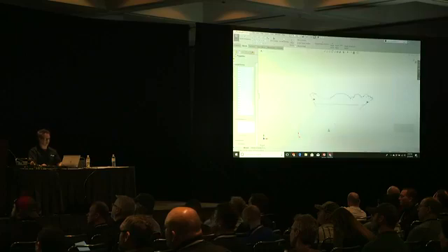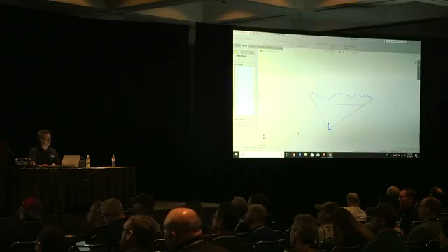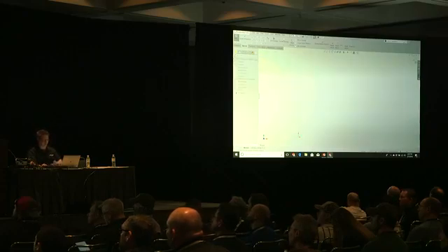I'm going to window select everything from my pop-up. I'm going to make a block. My insertion point, I want this to be right here. Now I've made a block. It kind of turns gray. Just to mess with y'all, I'm going to delete it. And then I'm going to insert it because I want it at the origin. And I want to be able to rotate it.